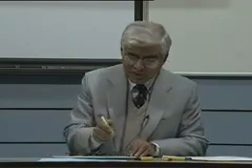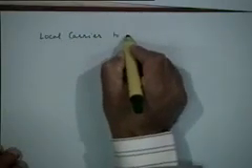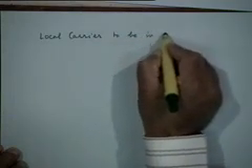So therefore this gives you an alternative method for demodulating SSB signals. Now that issue that was raised a couple of minutes ago about the phase coherence of the local carrier in this case, right? It's true. Even in this situation we would require the local carrier to be in phase and frequency synchronism.